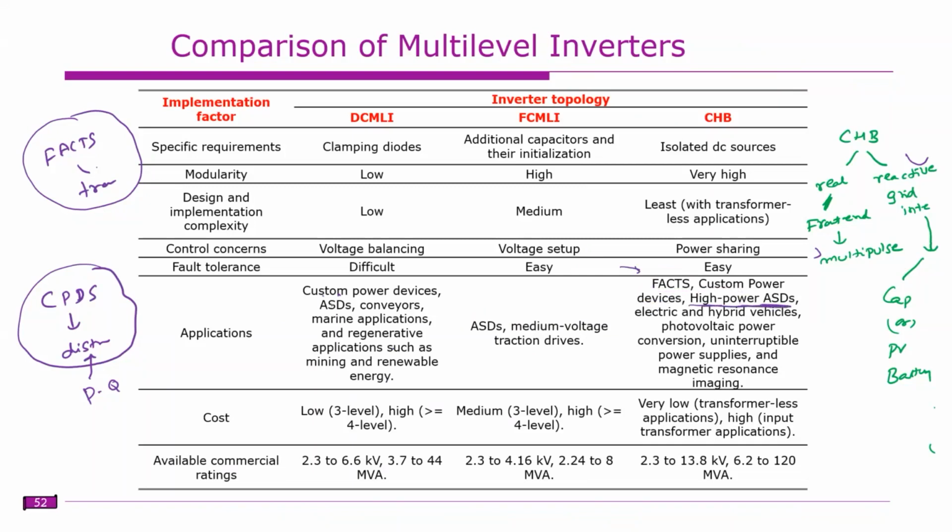The thing there, for adjustable speed drives or for motor drives, you must have a real power transfer. Again, if you have real power transfer, you require a multipulse arrangement. So that's why if you have a high power transfer in the range of 100 kilowatt or 100 megawatt, in case of steel mills, for example, you require a motor in the 100 megawatt range.